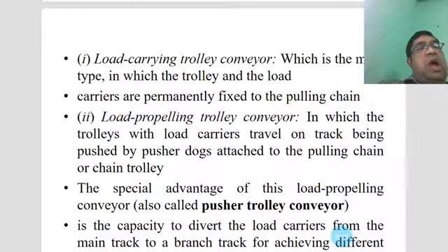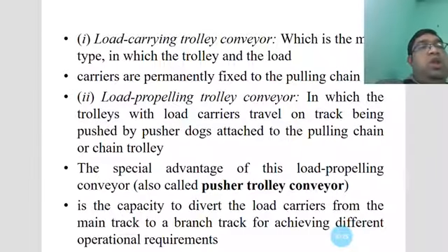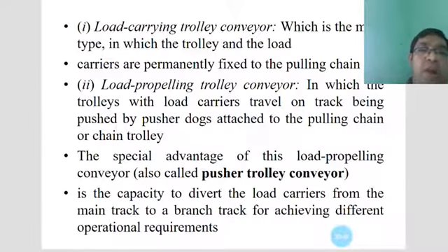And there are also load propelling trolley conveyors, in which the trolleys with load carriers travel on tracks, being pushed by pusher dogs attached to the pulling chain or chain trolley. The load propelling conveyor is also called the pusher trolley conveyor.